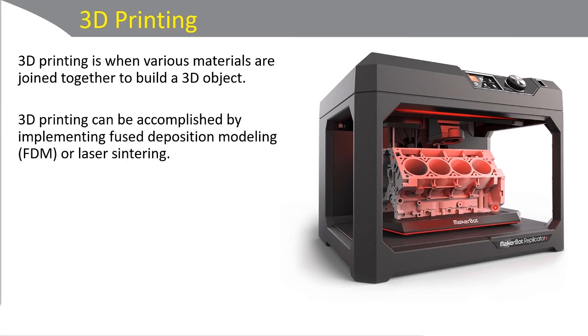And it's done layer by layer, ultimately creating the 3D shapes, which harden immediately. Laser sintering is a little different. That uses a laser that compacts a piece of material, such as nylon, using heat and/or pressure, and binds the material to create the structure. But FDM, very common in the industry.